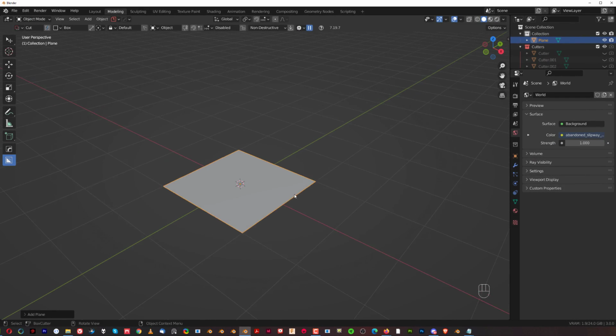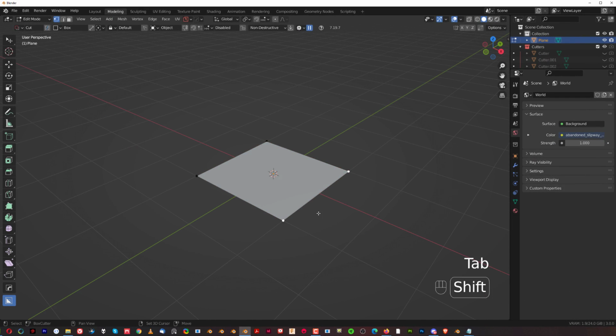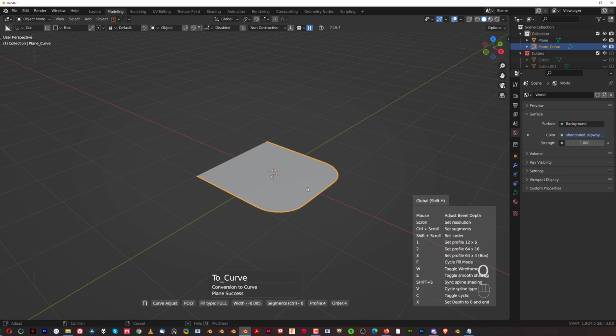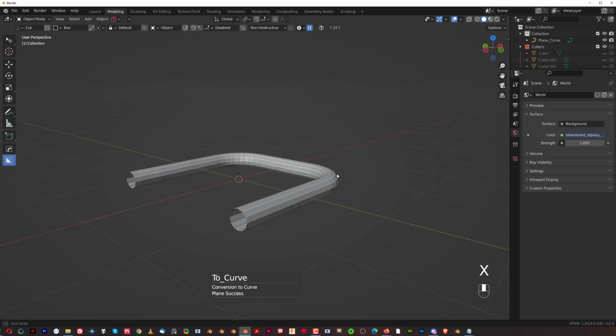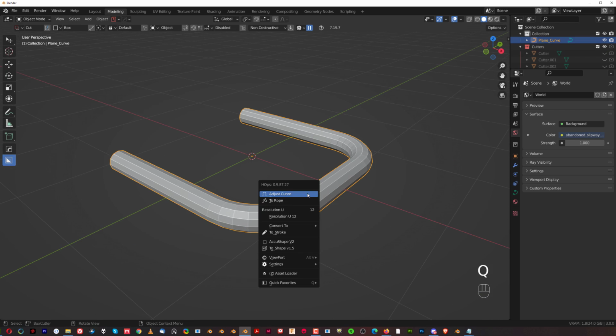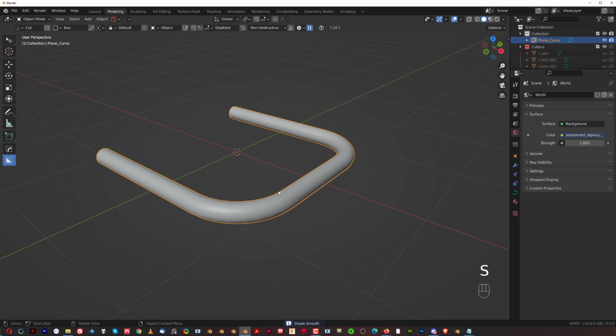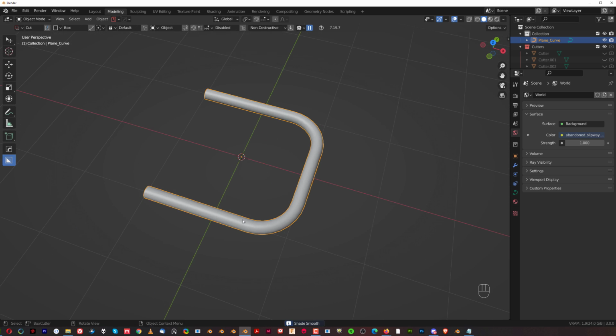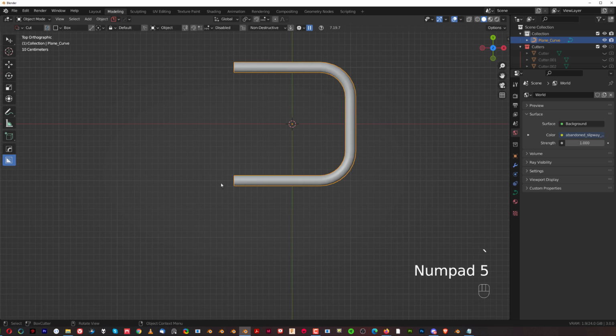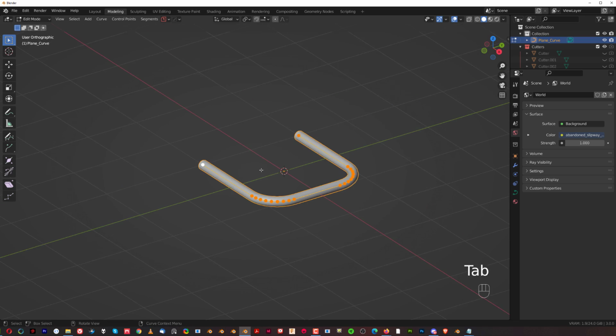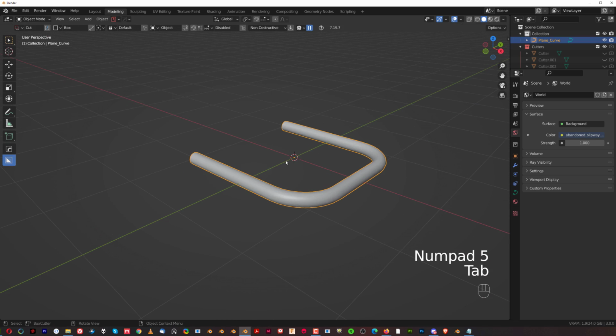Another cool trick that I'm using a lot is resetting curve. So let's Shift Control B that, and let's create a curve here like this, and we're going to go to Q and Curve Extract, right? So we got this curve, let's delete that. Now with this one being a curve, you can press S to smooth it. And then what if I wanted to change the size of it, or let's say continue with a really nice curve in here? I would need to convert it to geo. This wouldn't be that easy, but with HardOps there is a trick.